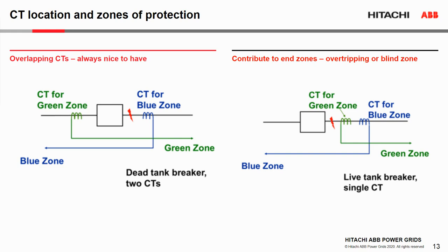But mind you, people also comment that the likelihood of a fault happening right here is very, very slim. That's correct. However, for strategic, important extra high voltage stations, which typically have freestanding CTs and live tank breakers, you probably don't want to wait. That depends on the stability studies to support this type of decision.